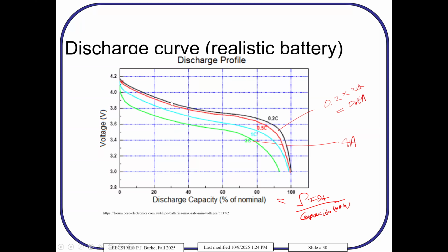So what'll happen is it'll be 4.2 volts, you take off, it's immediately going to sag to under 4 volts, even if you've only used a few percent. And then if you land immediately, you only fly for a few seconds, then it's going to go all the way back up to about 4.1 volts. So the voltage under load is going to be much lower than the voltage when it's not drawing any current.